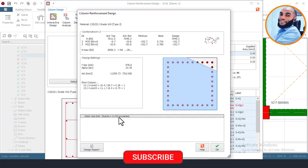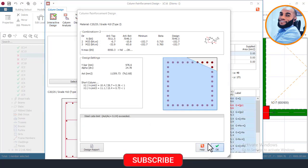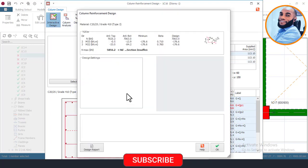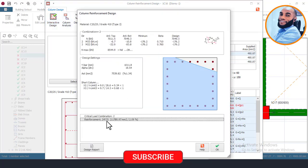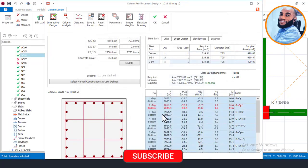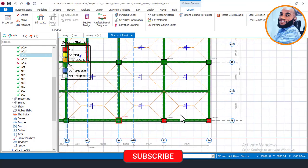Okay, it's not okay because of the pool side. The pool side is really having much weight. So I'll come here right now and use 750 for that, and 750 here also, and update, and then choose reset bars, and then come here, design, and wait for it to show. Yeah, that's fine. 24 numbers of 525, that's fine. And I'll come here right now and then say okay, and then final okay here. That's okay. So because of the pool area, that's why the load is being that.